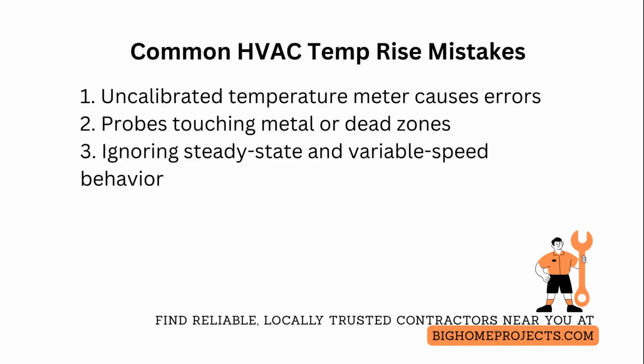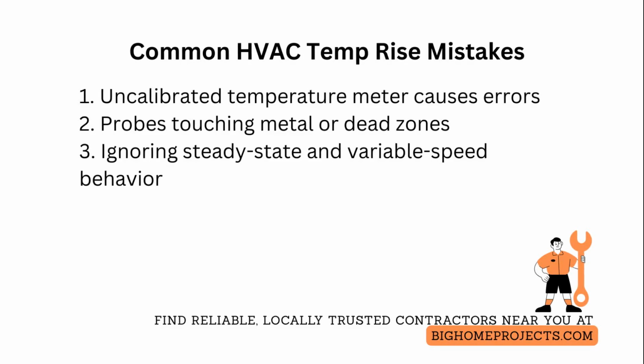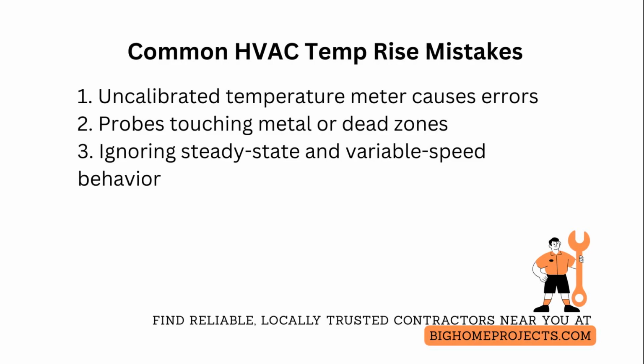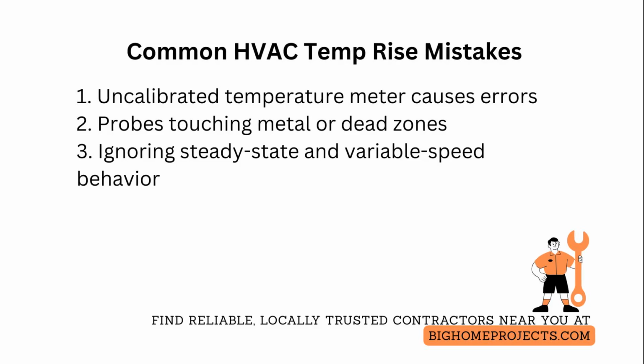One of the top 3 common mistakes is relying on an uncalibrated temperature meter, which produces sensor drift and error. Fix this by zeroing both probes before each test, performing periodic 2-point calibrations, and swapping probes to detect bias.